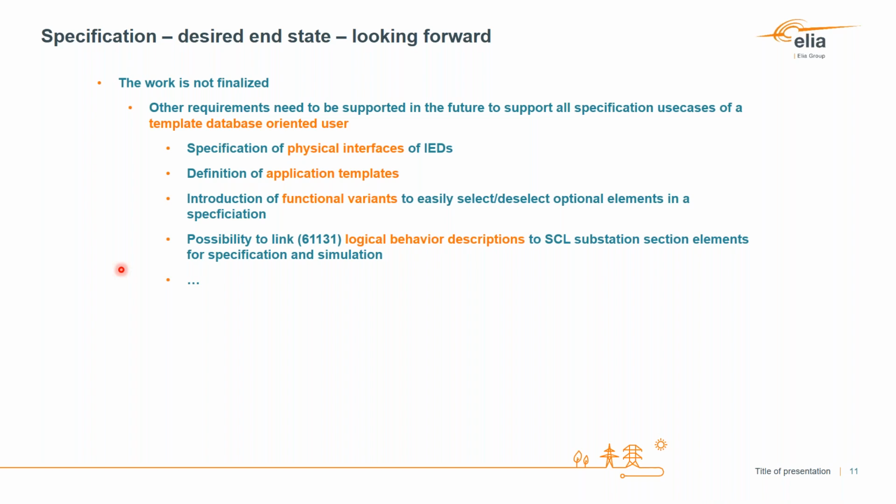For example, we want to be able to specify also physical interfaces of IEDs, so that we have the ability to specify if we want a signal on a binary input of an IED, for example, without having to specify the IED itself. Or, for example, wanting an analog value on an analog input of an IED. So we really want to be able to model the IED already in specification without having to include real IED or vendor information.